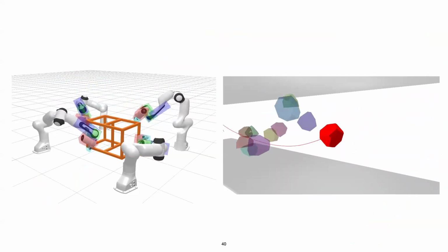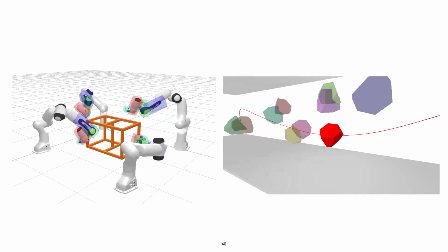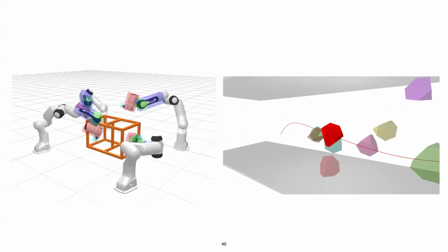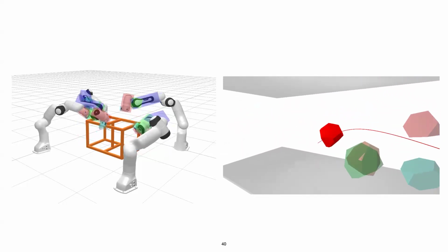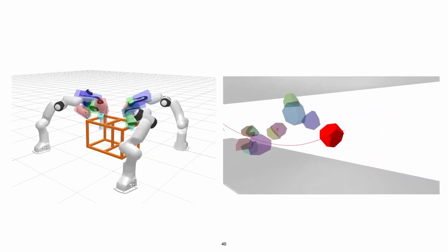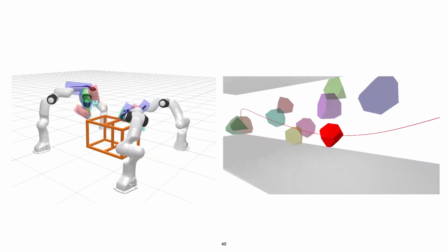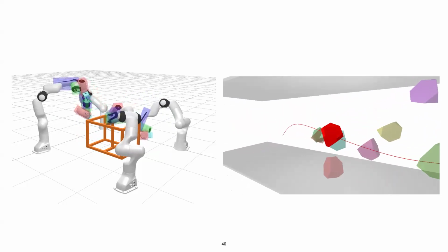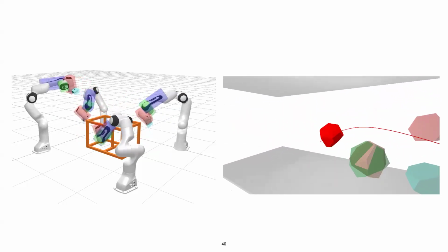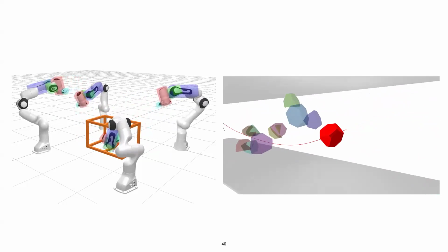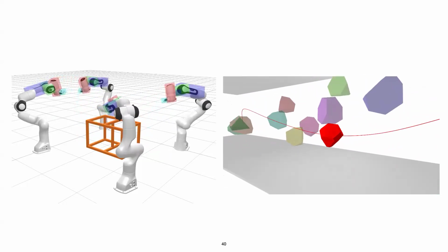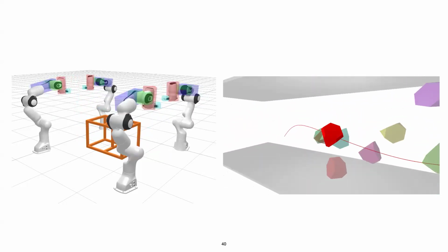And on the right, similar to the quadrotor going through the cluttered environment, I now have a polytope going through a sea of other polytopes, but now everything is moving. Basically the only difference in this problem is that all of the collision constraints are continuous. I'm representing what happens to these objects at the adjacent time steps, not just at the knot points themselves.